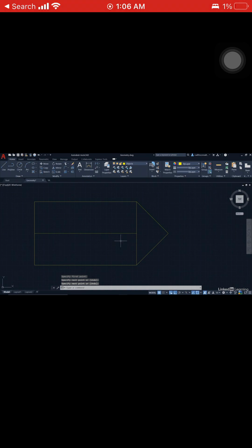Talking of vertical, let's repeat that. Let's go back to the line command. I'll go to this midpoint now, and as I come down, you'll notice I'm moving the crosshair. Can you see I can only go vertically or horizontally? So I come vertically down, hit the midpoint there, left click, enter to finish, and I don't even need my object snaps on to get those midpoints because I know that they are orthogonal lines. They're vertical or horizontal and they're true. They're going to be exactly horizontal or exactly vertical.